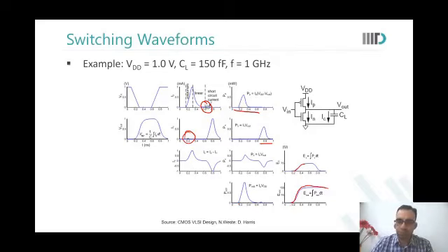Why is the current rising initially? It should be maximum, then it should fall, and then rise again. Why should it rise? The direction has changed, is it not? When the capacitor is discharging, the direction of flow of current has changed, so it will appear as negative current. But when initially it is charging, the current should be falling, right? Yes, the current initially would rise and then fall. Once the capacitor starts to get charged, the current would fall. That is why the current fell.